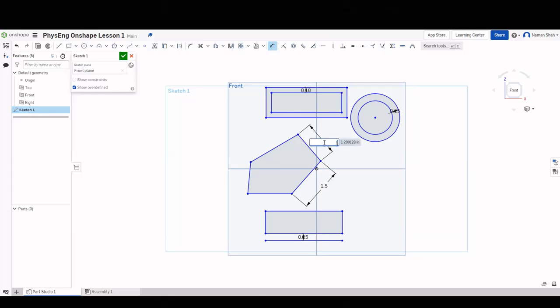And doing so, you can actually add specific qualities and you can add finer details to make a part exactly how you want it to be. And that's one of the brilliant things about CAD, because you can never be too accurate in real life, but in CAD you can be 100% accurate 100% of the time. One interesting feature about this is, if you select the line, you'll end up getting a length, but if you select two lines, you can actually dimension the angle as well. So I could change this to, let's say, 110 degrees, and it'll adjust accordingly.